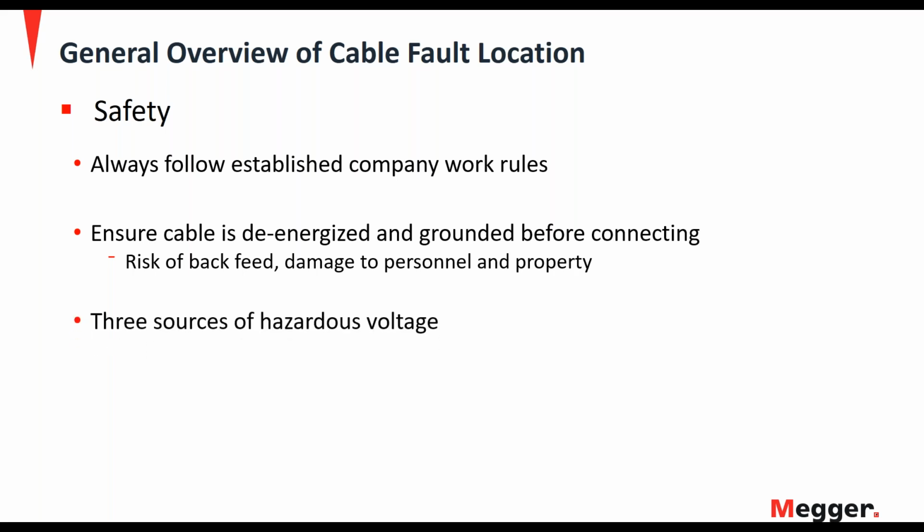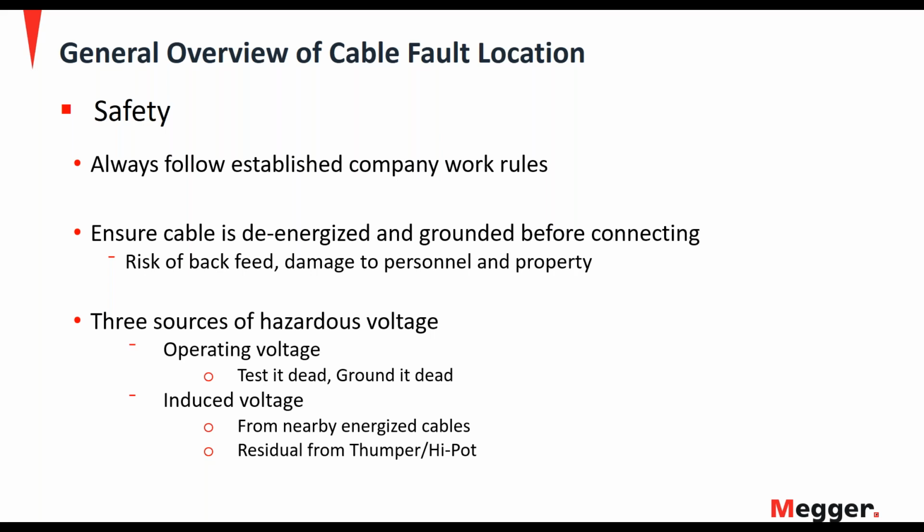While you're working with a thumper out in the field, there's three sources of hazardous voltage that you need to consider. Obviously, there's operating voltage, and you'll have gone through the appropriate test at dead, ground at dead procedure. Because you're working on a cable, you could have induced voltage from nearby energized cables. You could also, if it was a good cable, you might have residual voltage on the cable from the work you did with your thumper or hipot. In other words, you may have charged up that cable.